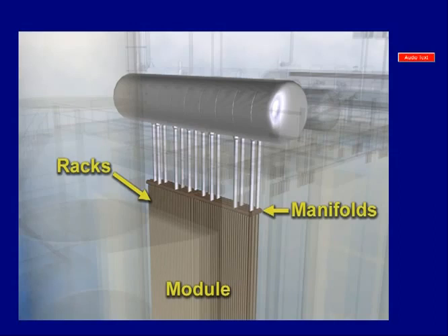Boiler racks are rows of finned tubes that are welded to distribution and collection manifolds. Boiler modules are composed of racks which are arranged together. The inflow to outflow in a pipe rack can be from the top header to the bottom header, or from the bottom header to the top header. The headers of adjacent boiler racks are placed against each other in order to avoid bypass flow of exhaust gases outside the modules.